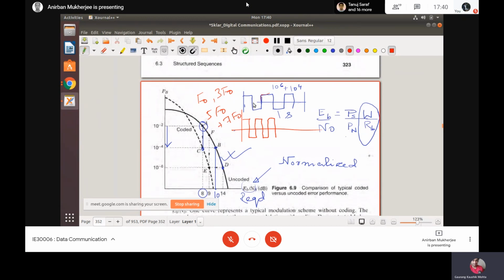So if you do the Fourier series of this one, it will be coming like that. So that means sin 2 pi F0t, then sin 2 pi 3F0t, sin 2 pi 5F0t, 7 up to infinity, as it is a square wave kind of thing. But after the 7th harmonic, you have seen that this is very small, so it's okay to discard.